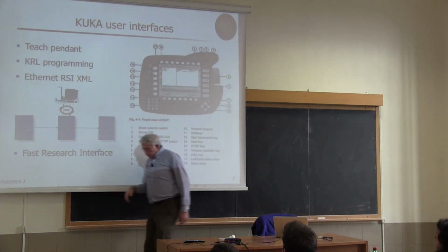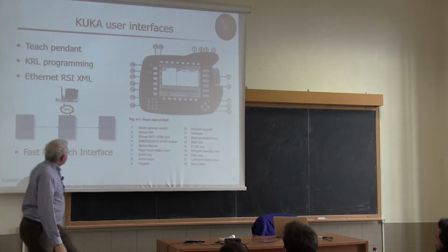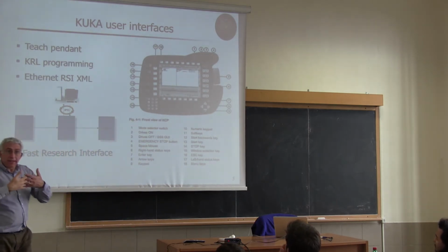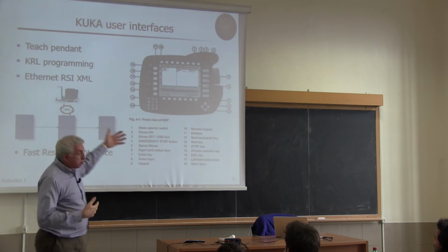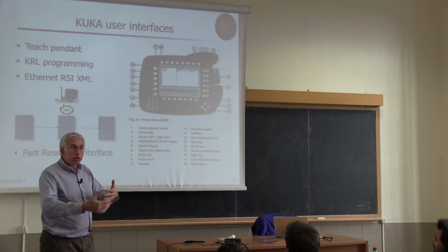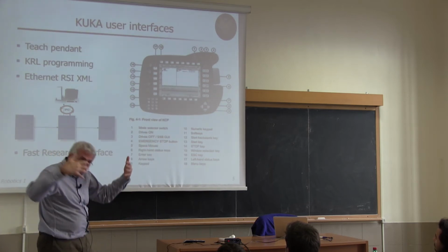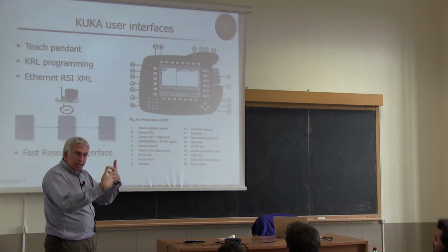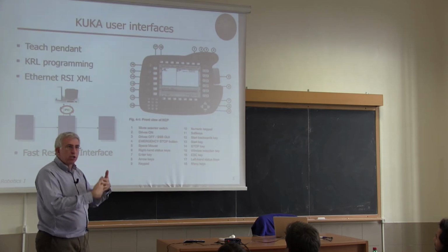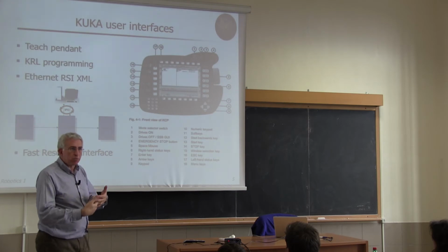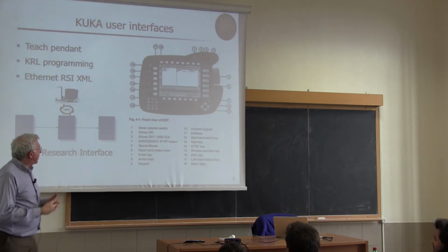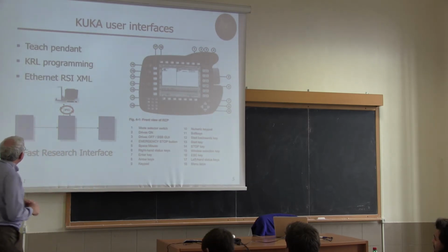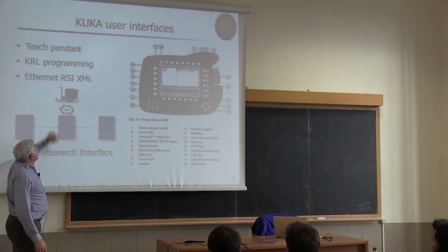Then there is the programming through the KRL language, and the two things are integrated. So you can instruct some motion through the teach pendant by moving the robot, or write some code, or merge some skeleton code generated in this teaching mode with some other part which you programmed offline, and do things like that.